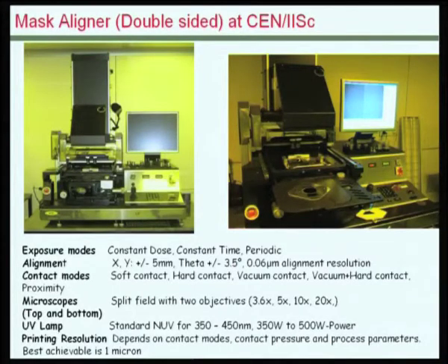In a typical process flow of building a microsystem or an IC, we need to register where the reference points are, so that the subsequent layers one over the other are aligned with respect to some known references. It is possible to do that by accurately positioning the mask plate above the wafer.